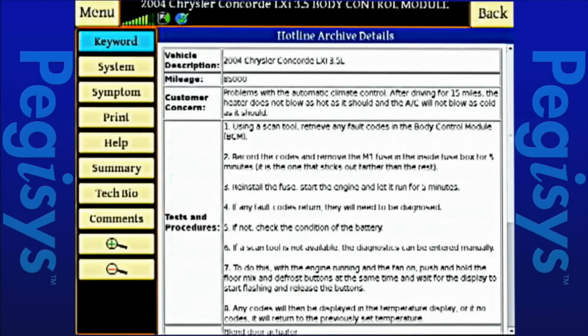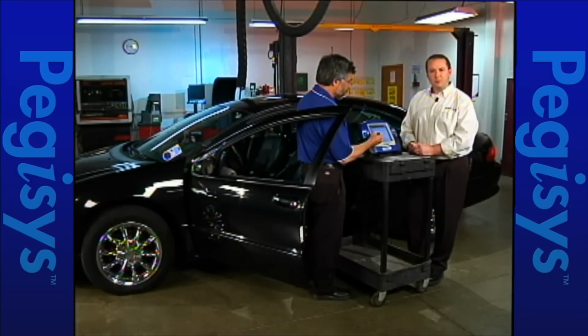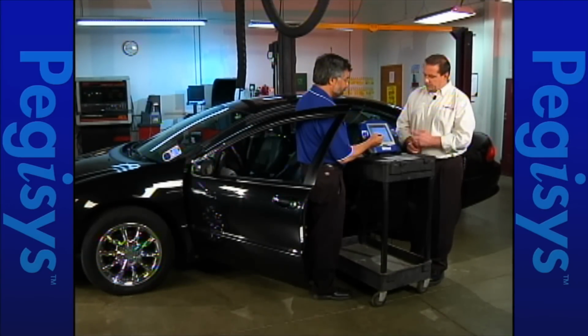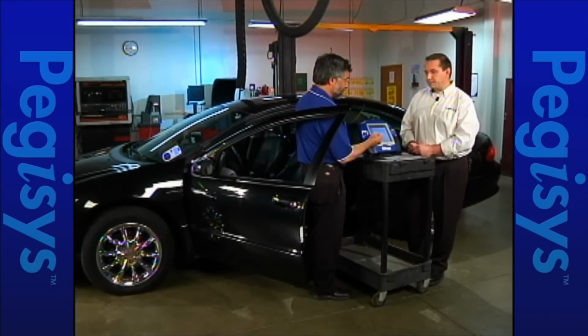Now I'm going to focus in first on the top area where it says customer concern. It says problems with the automatic climate control. After driving for about 15 miles, the heater does not blow as hot as it should, and the AC will not blow as cold as it should. Well, that's very similar to the symptoms we have from our customer on this particular vehicle. But let's go ahead and dive into this particular archive and see what steps we're going to do to diagnose this problem.